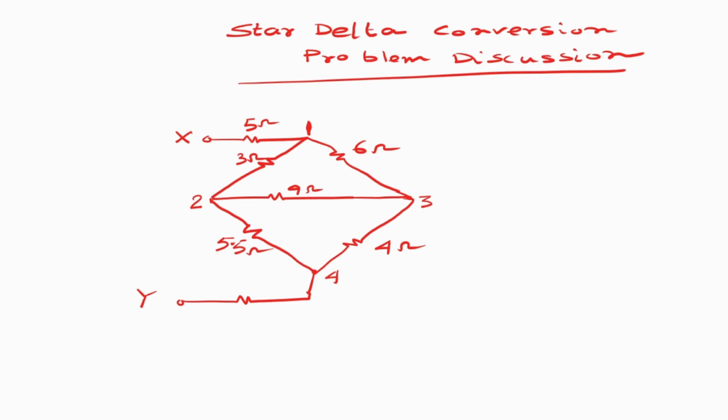How do you select? If the resistance network is given, first you should determine which resistors are in series and which are in parallel. So the process is that, when you determine the equivalent resistance between these two terminals, we imagine a current source between these two terminals, terminal X here and terminal Y here.